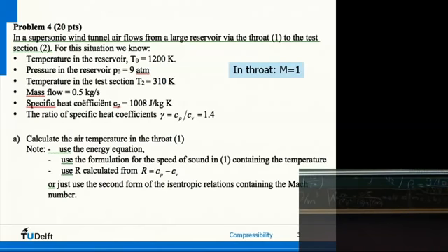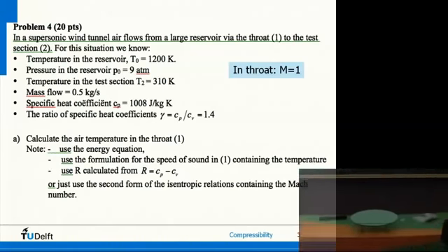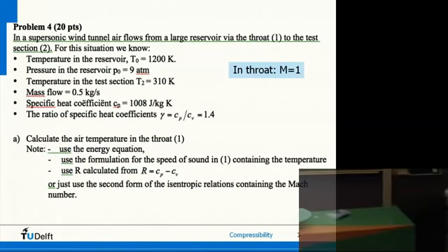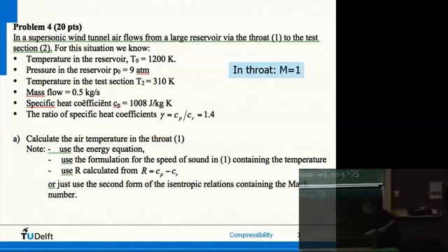So the area is like this. So really a very strong contraction. That you will see quite often for supersonic flow. If you look at our hypersonic wind tunnel, we have a wind tunnel where we can obtain a speed in the test section of Mach 11. We have a very strong contraction ratio. Also the flow expands very strongly, and then the flow compensates, so we can only measure for 1 millisecond. Is this clear? Any questions about this? So maybe for some people.